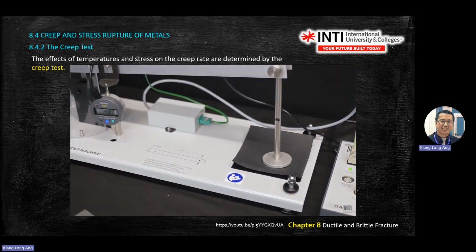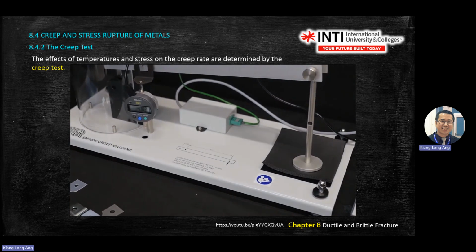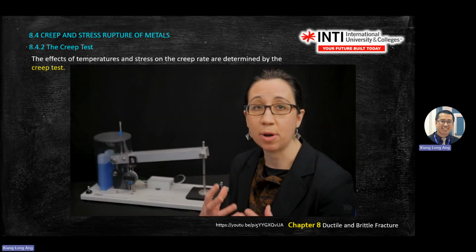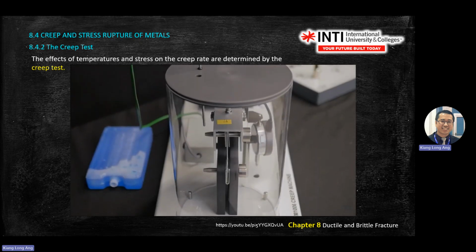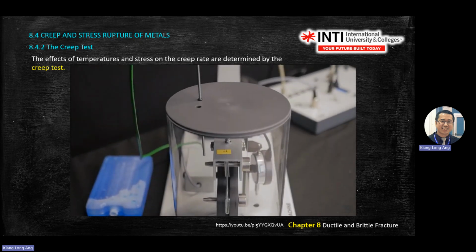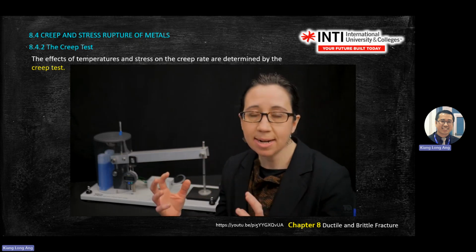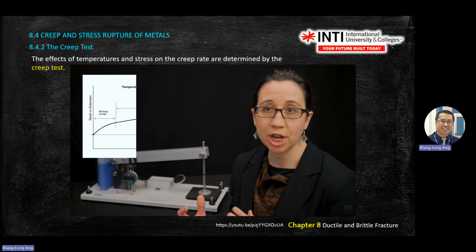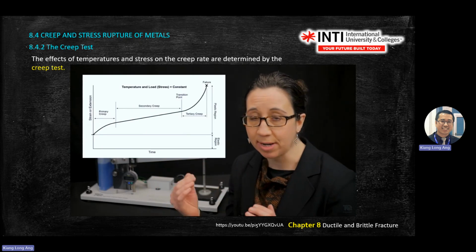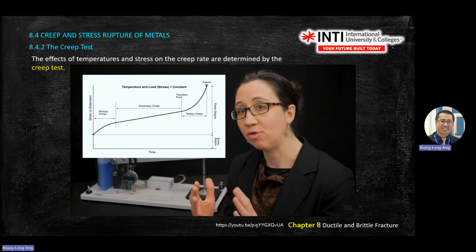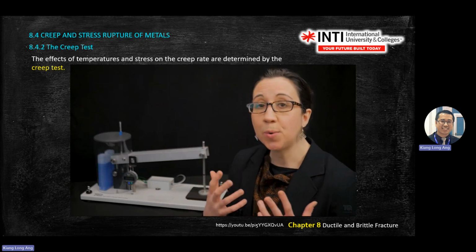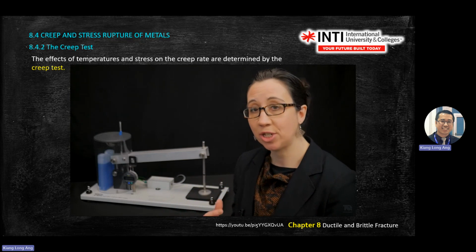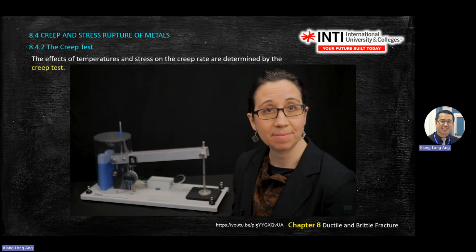This is one of the many experiments within the materials testing and properties range from TechQuipment that allows you to witness the normal breaking load of lead and different plastic specimens over a fixed time. Look at the relationship between breaking load and time for lead specimens. Create time extension curves to show the three phases of creep, that is primary, secondary and tertiary. You can also look at the effect of temperature on the creep rate and establish the creep rate for different specimens.